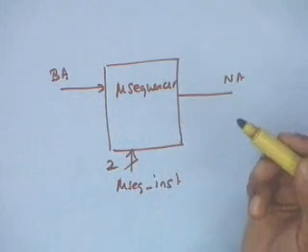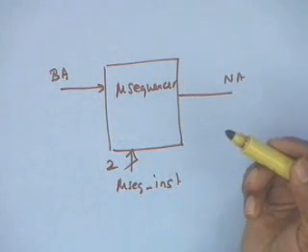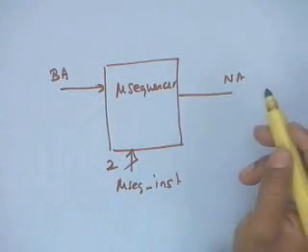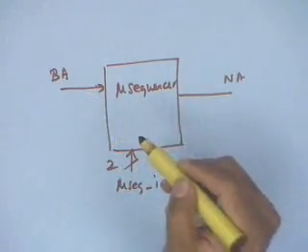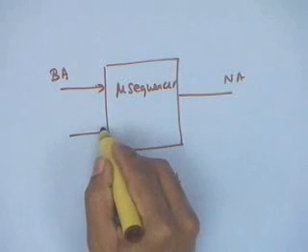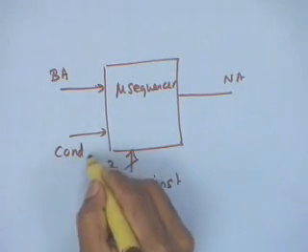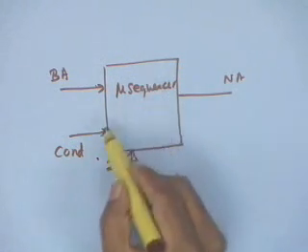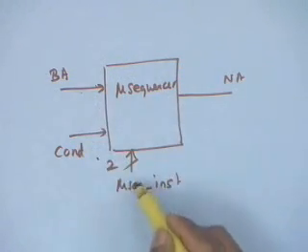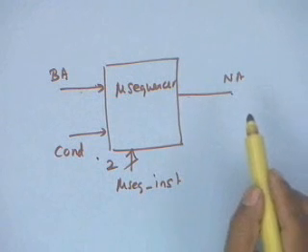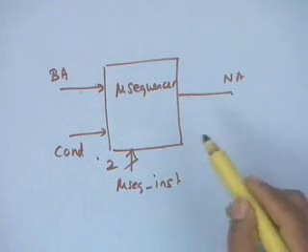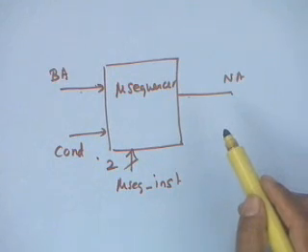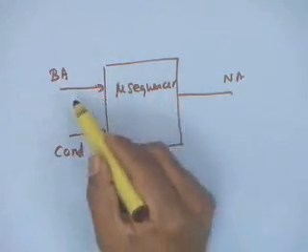Branch address is needed whenever you are doing a conditional branching or an unconditional branching; I need to generate this branch address. Get it? We will talk about what the size of this is in a moment. The other thing it gets is a condition. So based on these 3, branch address, condition and microsequencer instruction, this generates the next address from the present address. Previous address is not the input, this is the input.